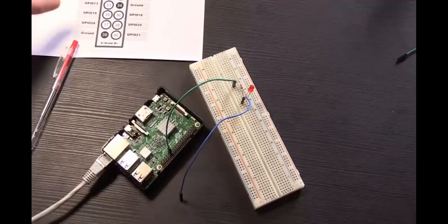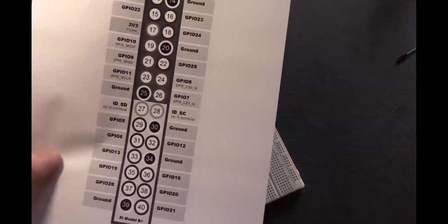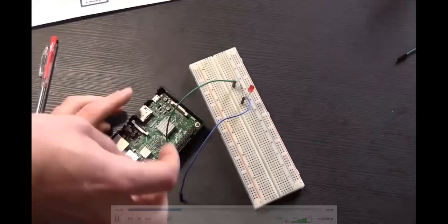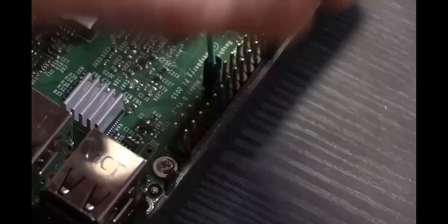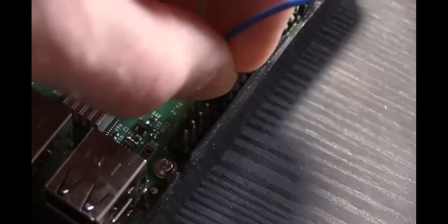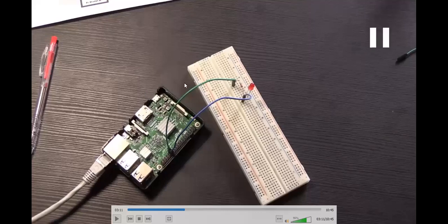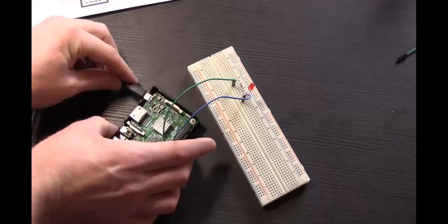And we can see from the same chart that if we want to plug it into ground, next to GPIO pin number 5 is a ground pin. So we can just stick our ground pin on this side of it. So have a quick check over once again, just to make sure that you've got all of these things in line. So this is very simple. This is how we connect an LED bulb with Raspberry Pi. If you can connect the LED bulb, that means you can connect whatever the components. Once everything is right and in place, take your power cord and boot up your Raspberry Pi.